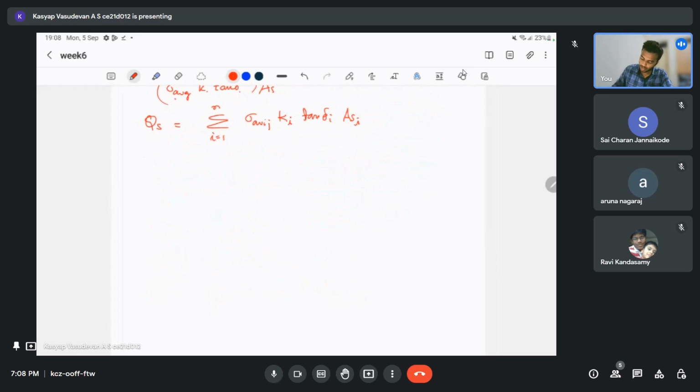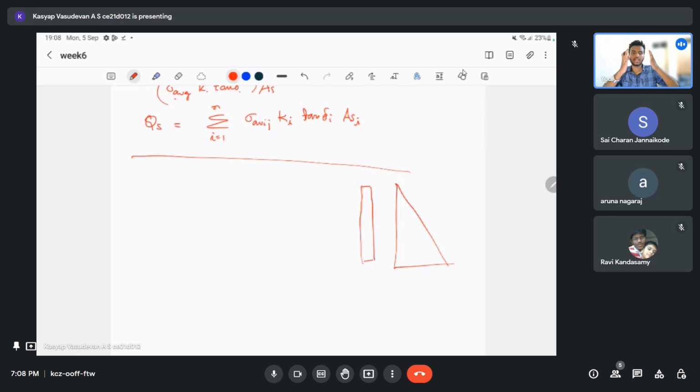Another ambiguity here is we are dealing with the profile. So till now we only assumed that the trend of the vertical stress is linear. That is the most simplistic idea, but actually it is not linear in reality. Depending on the soil, it varies, and it can be something like this. And as we go deeper and deeper, this can get linear also. So that's when we come up with a term called critical depth.